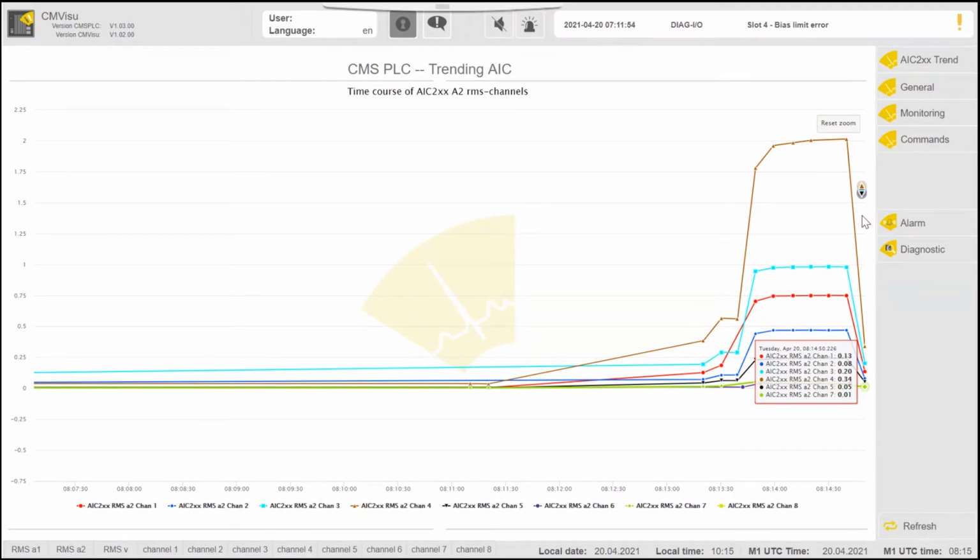So what's happening in the background is the monitoring system is taking a detailed measurement from the machine every now and then, every hour or so, but you have these continuous overall levels showing what's going on with the machine, and you have continuous alarming. So if something suddenly changes and a vibration goes up, then an alarm will be triggered, and the system can take a sample of more detailed data from that point.